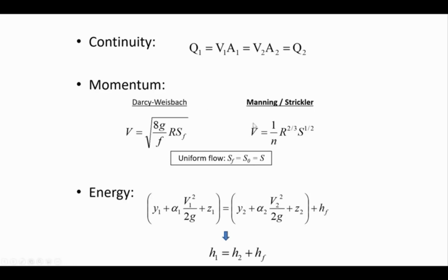All right. So I told you that we don't usually have f values for open channel flow. There technically is a Darcy-Weisbach equation that relates flow velocity and f values in open channel flow, but the Manning equation is far more convenient and gives us a good enough answer so that we can use constant n values rather than variable f values in our calculations for velocity.